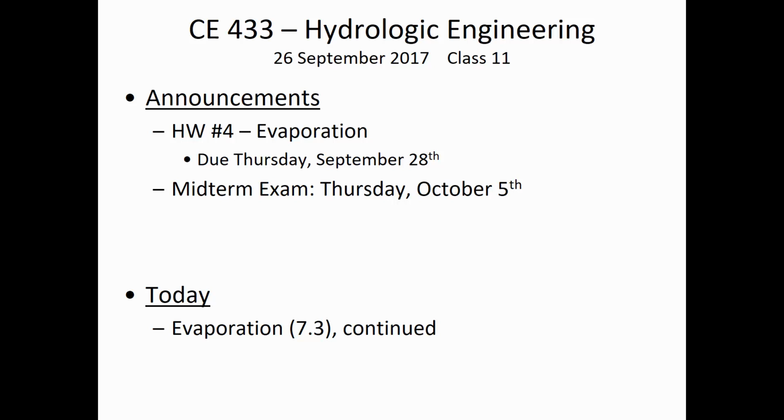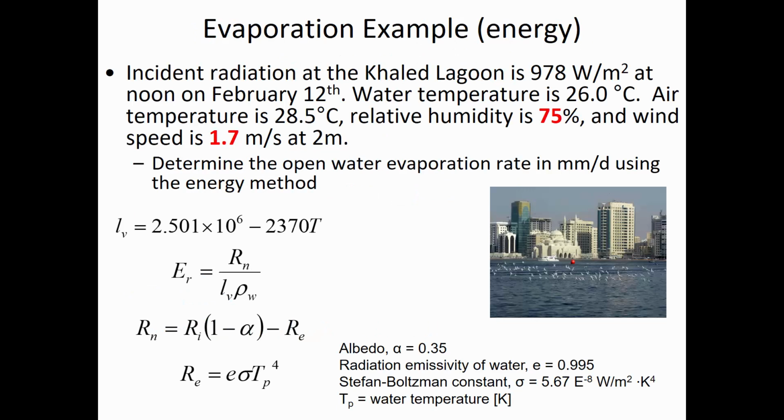All right, we're going to continue talking about evaporation today. And last time we left off talking about the energy method. Who wants to take a crack at summarizing the conceptual basis of the energy method? What is it? It's predicting evaporation on the basis of what? All right, the sun coming in and coming out. So the difference between the two, the incoming solar radiation and the outgoing radiation that's emitted, the difference between the two is free energy that's driving evaporation.